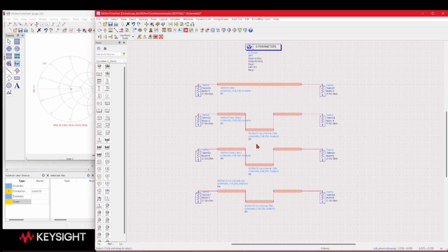What I'm going to be doing next is trying 3 different calibrations, so the internal port options available here. As you'll see, I'm breaking this line into 3 pieces of the same length. The center one is always going to be the same, just 1/3 of the line with TML calibration at both ends. In all 3 cases it's actually the same circuit, or the same structure. I can use TML because I'm going to have free space around it here, and I'll show you the setup in RF Pro later.